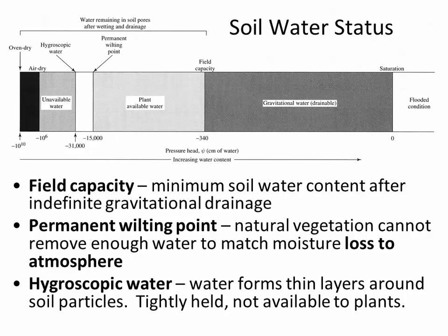And this hygroscopic water is tied to the diagram that we were looking at before of the wilting point, where the wilting point for clay is very high because there's more hygroscopic water. It's the water that's used to wet the surface. There has to be a lot of that water available wetting the surface of the clay before there's anything left over for the plants to remove. But in the case of sand, it needs less water to wet the surface because there's less specific surface area in the case of sand than for clay.